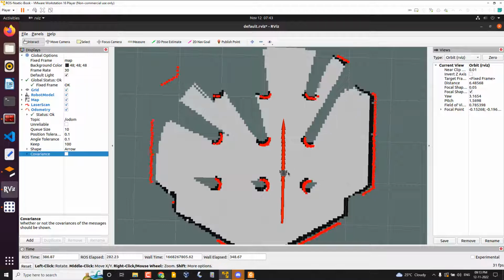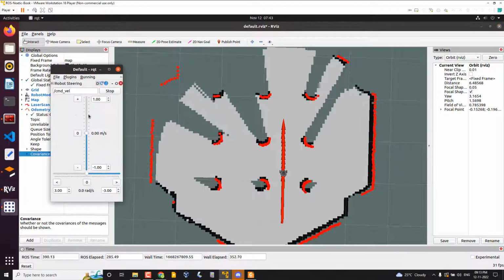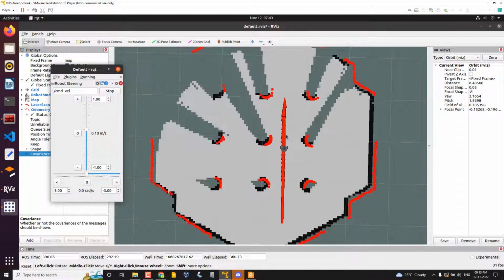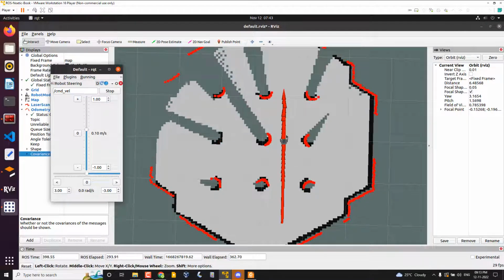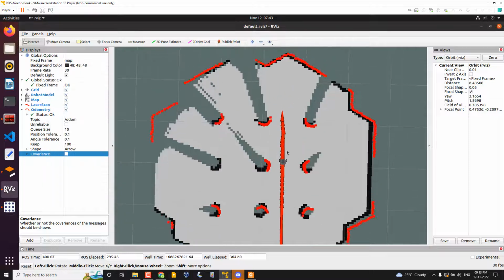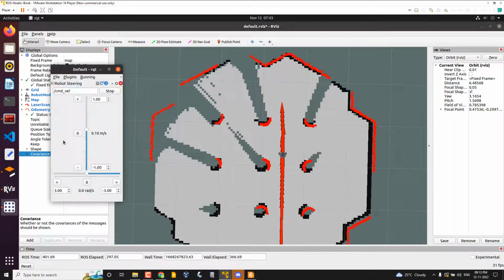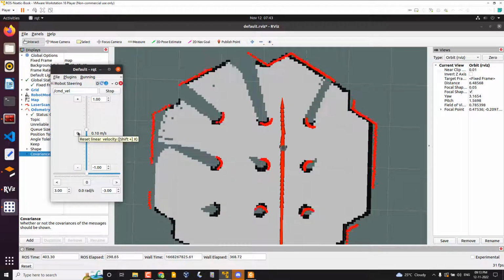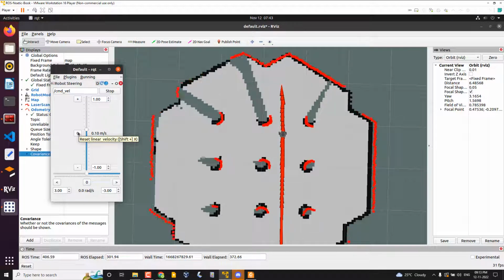That means the robot is actually mapping and also localizing. It's creating the map of the environment by taking account of the obstacles. So the main input here is the laser scan that you can see, and also the wheel encoders. We will get back to that anyway. This is just a demonstration.